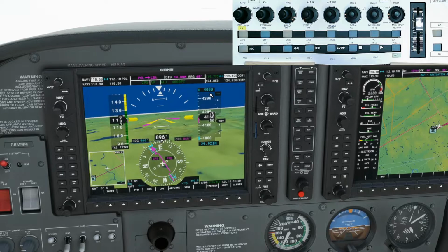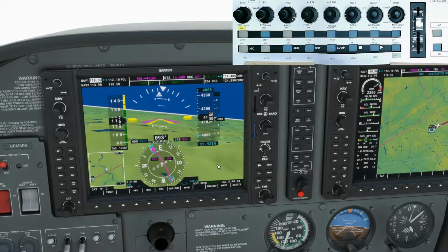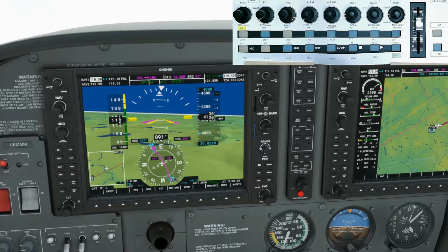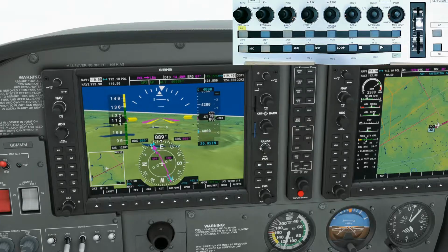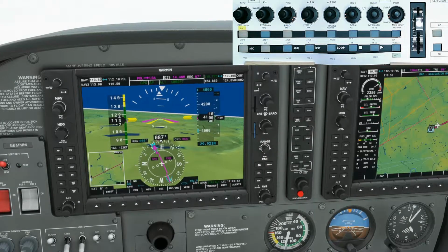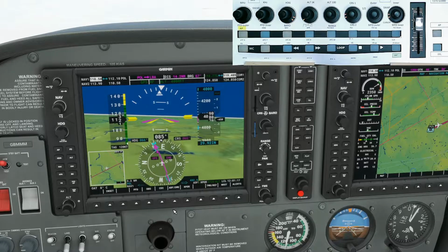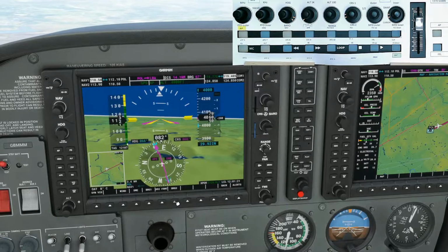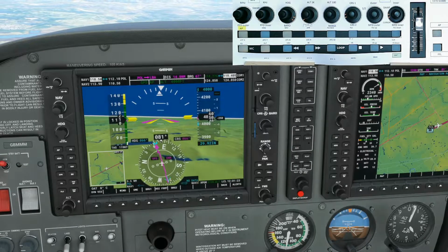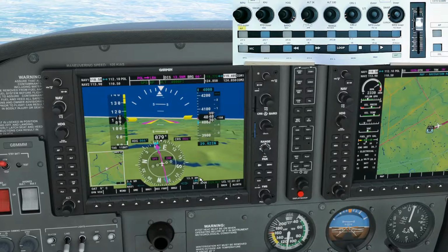And I'm just waiting for this to stabilise now at 4,000 feet, because we're going to lose some airspeed as we level out. What I can do now is I can change this on the PDF, and the bearing 2, I'll bring it to GPS. So it tells us how far we've got to go to Leeds Bradford.